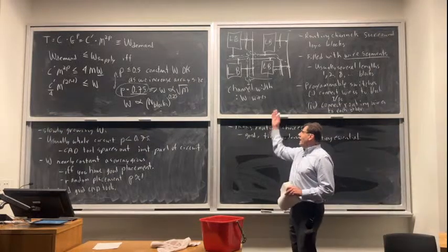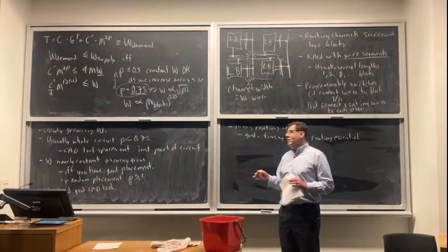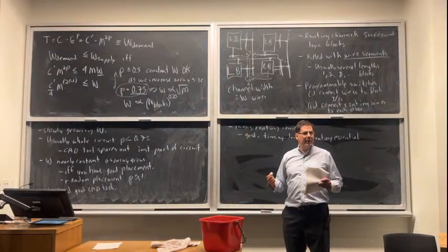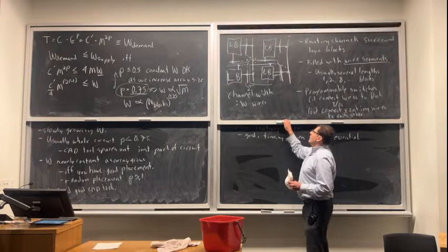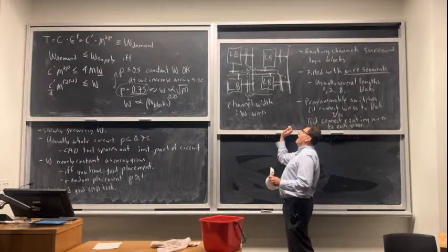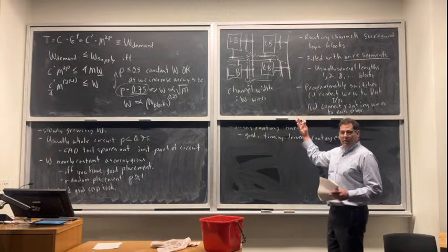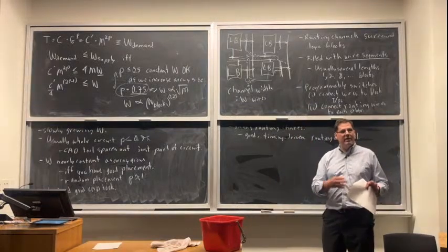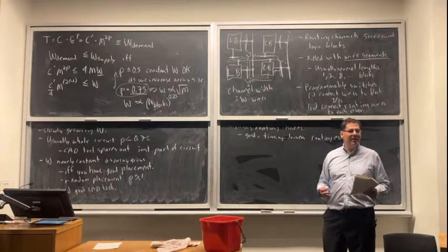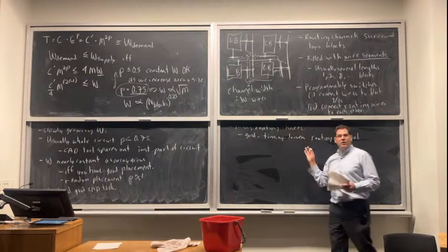And they had actually analyzed this kind of architecture, these island-style architectures, and they concluded they were bad. But the reason they concluded they were bad, well, we're pretty sure, is because their router wasn't good enough. Their router didn't do a good job of sorting all the options. So when they did experiments with these kind of chips, they decided they weren't as fast. So we did redesign their architectures to this style. We deployed the CAD tools that my company had created, and they did work better. But the reason I bring that up is, yeah, it's evidence that you really do need good timing-driven routing,